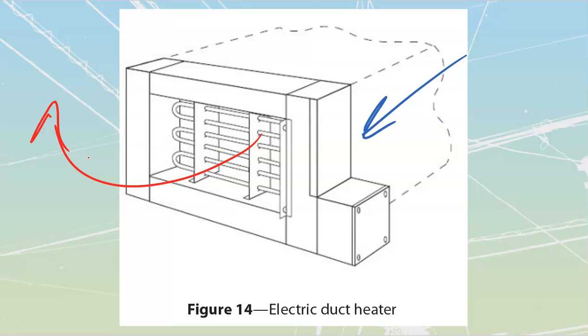Usually these are going to be more inside of a three-phase commercial type of system that we are going to see, where we're going to be able to individually turn these on and off. In fact, inside most of our HVAC systems, we're going to have radiators that we're going to be able to choose whether to heat or to cool. But inside of a residential application, just inside of really large ones, you might see these electric duct heaters. If you do have them mounted, they should incorporate some sort of a sail switch, also referred to as an airflow sensor, that is going to prevent this thing from operating if there's no air being pushed through.